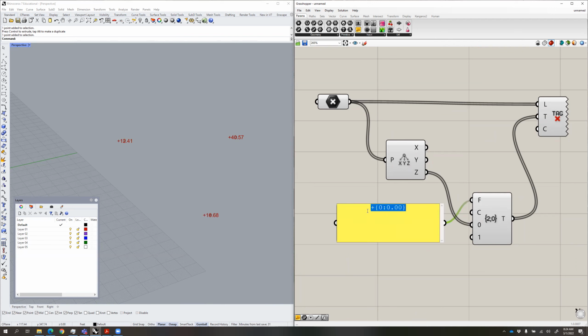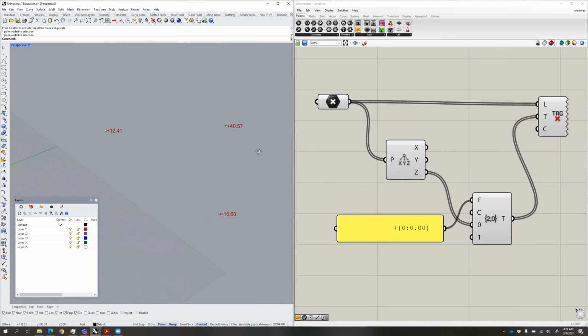And then one little fun trick is if you add a bunch of spaces to the format, you can begin to shift that over so that it feels a little bit more centered on that point. So now what we've done essentially was we've created right here a spot elevation tool. One of the simplest tools you can have, but maybe all you want to do is model a project and you just need to know the spot elevation. Voila, you got a spot elevation tool.